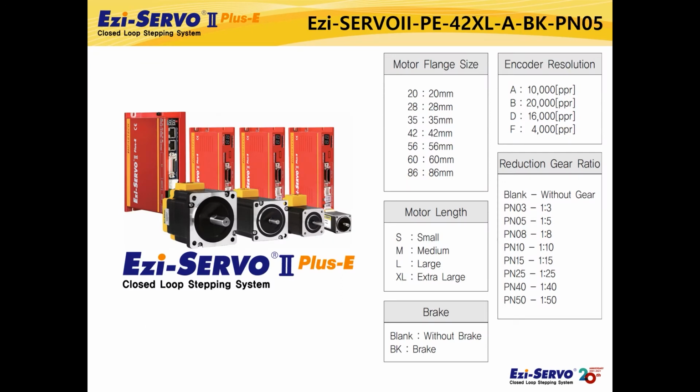First of all, I will explain the combination model name of Ezi-SERVO Plus-E product. In the example model name, PE means embedded controller with Ethernet network, 42 means 42 mm motor flange size, and XL means motor length. A means a product with 10,000 ppr encoder applied. BK means that a brake is attached to the motor, and PN05 means that a planetary gearbox is attached to